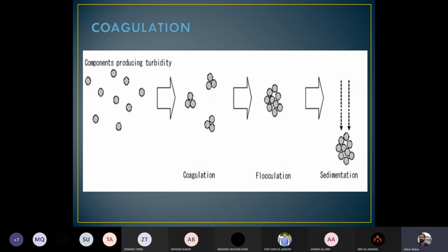There might be presence of microorganisms over here, and these microbes will be traveling along the water towards the filtration. If some of the microorganisms are removed in the filtration system, the remaining portion will travel to the disinfection system, and at the disinfection setup you must remove all the community of the microorganisms so that the water is considered safer for drinking water purposes.